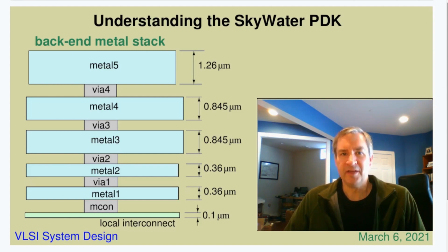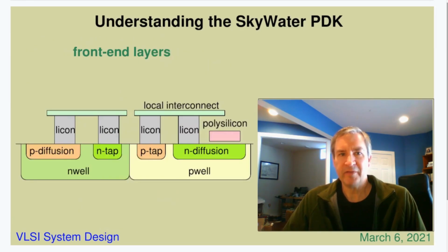Metal layers and vias are called the back-end layers, and everything below that is called the front end. They are often distinctly separate with different precision required for the masks and, of course, different fabrication steps. They share the steps of oxide growth, which is the insulation layers, but the front end is mainly diffusion and ion implantation, while the back end is mainly metal deposition, usually by sputtering.